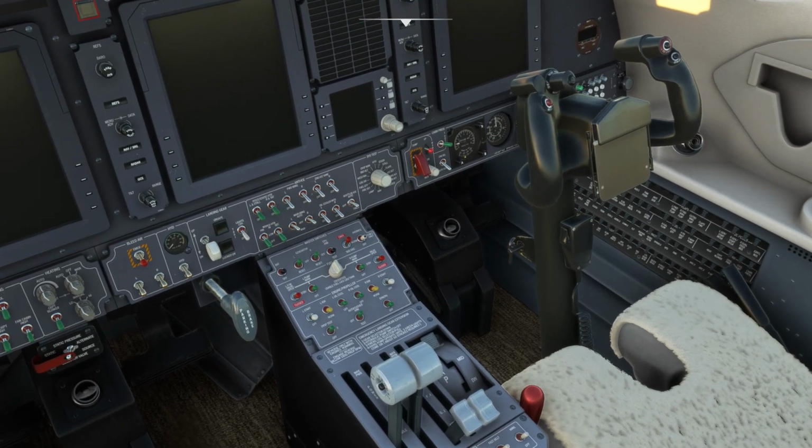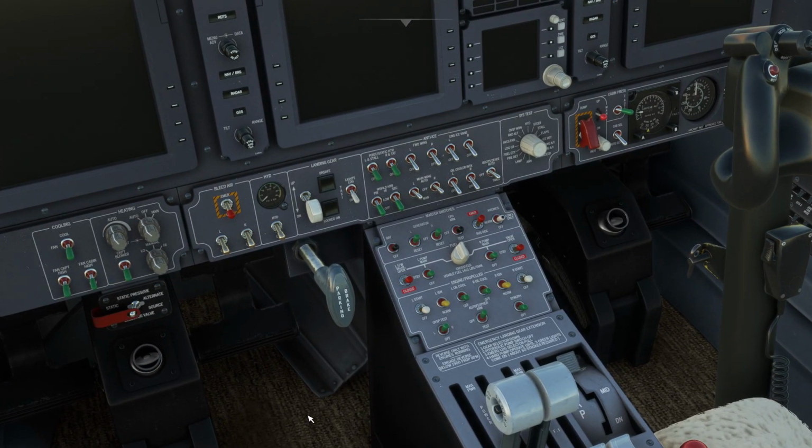Battery switch. So generally, the fantastic part of this aircraft is that nearly everything is electrical, and pretty much what you see on the screen is the whole panel operating the aircraft. That's the electrical panel. These are fuel pumps, a bit of engine management, oil coolers, anti-ice systems, which are quite pronounced. System test. This is your hydraulic panel. It's literally one display, one switch. Bleeders, heating, cooling, and then cabin pressurization. That's it. So, going further.